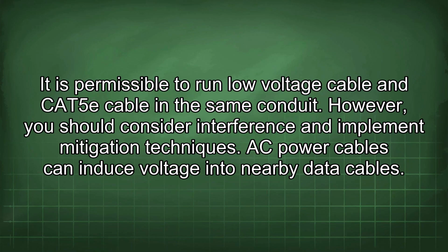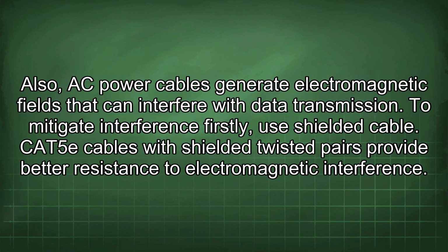It is permissible to run low voltage cable and CAT5e cable in the same conduit. However, you should consider interference and implement mitigation techniques. AC power cables can induce voltage into nearby data cables. Also, AC power cables generate electromagnetic fields that can interfere with data transmission.